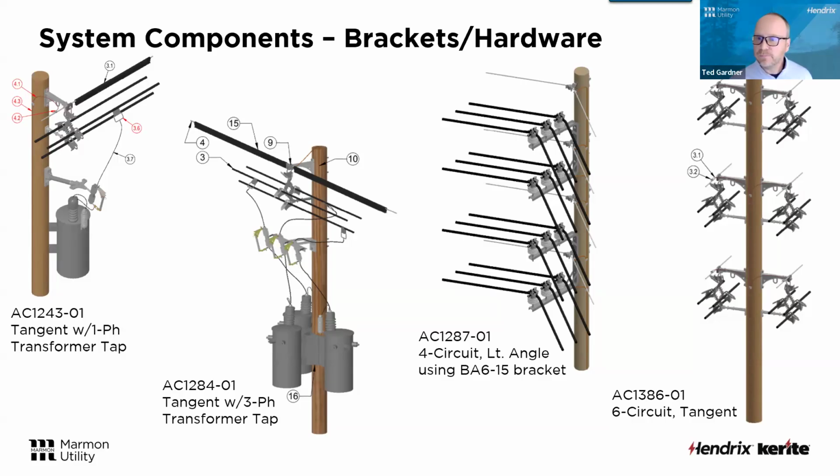Again, we place all of that load, wind, weight, surface area, all of that on the messenger. So that's what we're focused on. We've got standard construction drawings for stacking 4 circuits, and you can take that same angle, double up on those pins and insulators, and turn up to a 90-degree angle. With the lack of tension on those phase conductors, there's quite a bit of flexibility. We can roll those phases vertically and dead end them. We can spread them out on a cross arm like this.